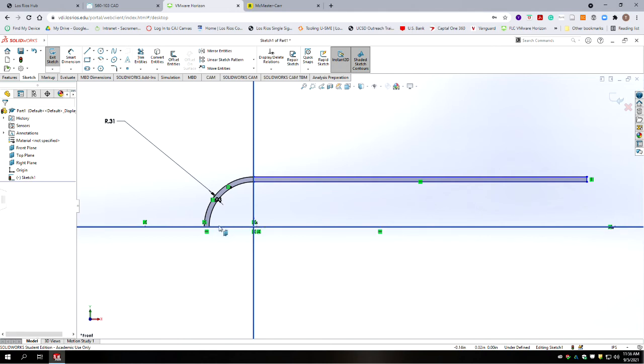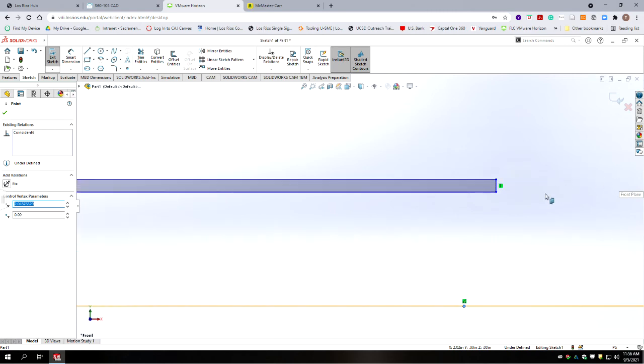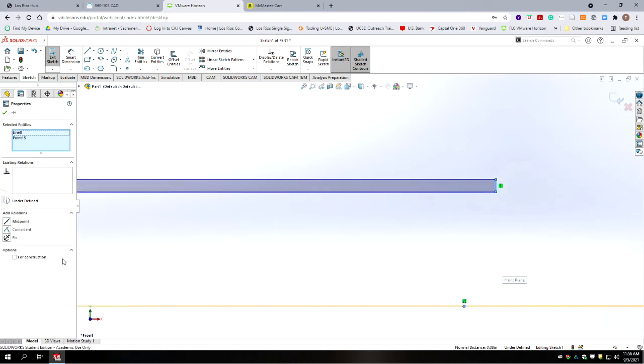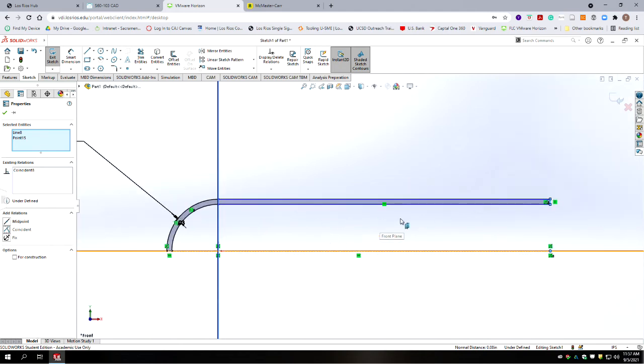Now, this kind of thing can be something that would make your sketch unconstrained if you don't put a length on it. So just for good form, we're going to go ahead and drag this line so that it has relationships with our sketch. So I've aligned it to merge with the end on the one side, and we're going to make it in line vertically by using coincident. So no matter how long this tube becomes, the length of this center line will be the same.